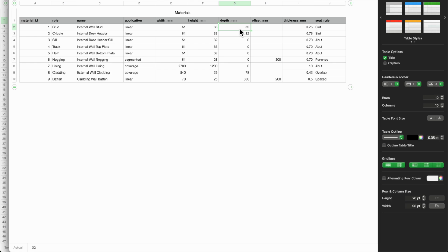If you're working with timber, you'll use a butt. So you butt the timber and then you shoot your nails in from the side, or however they do that. And then noggins are going to have two different combinations. If you're working with steel, you've got a continuous length of noggin, which is segmented by punched holes.